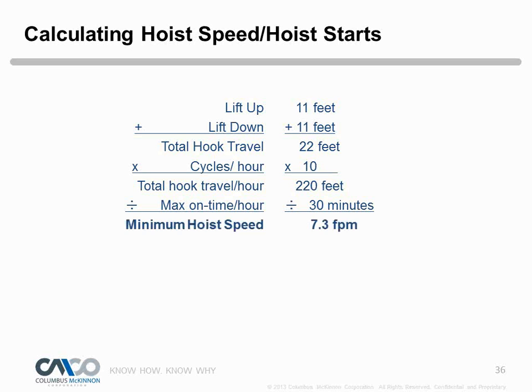So in this case, probably speed's not an issue for us. A standard 16 feet per minute hoist would work. But you may find that we need a quicker speed hoist to do this, otherwise we're going to exceed the duty cycle. If the hoist is too slow, you could run through that duty cycle quickly. We want to make sure we get a fast enough speed. Or, let's say it's a precision lift, we don't want to size the hoist to go too slow either. Maybe we size one that's 6 feet per minute. Okay, this is very precise, but given the parameters, it's too slow.